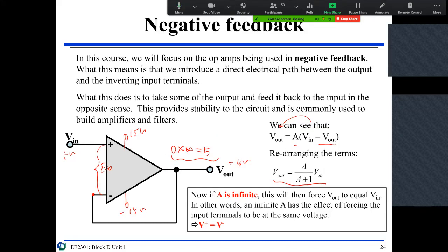Very, very small. So this is called a negative feedback configuration, and this actually serves as a voltage follower. Out is in. So you remember, I had a 0.5 in here. I want you to add an op amp in here, then you put 0.5 again here, like the voltage divider we did in quiz 3A. So quiz 3B is to put this guy in here.